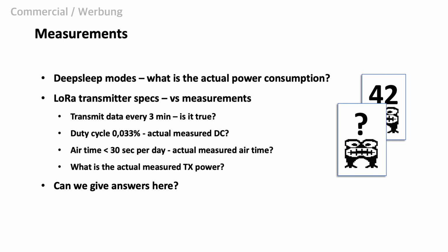We kept the default value of spreading factor 7. With that default, the LoRa transmitter is active for about 60 milliseconds, which we can find out from the LoRa specifications. In our case, we repeat a transmission periodically every 3 minutes.